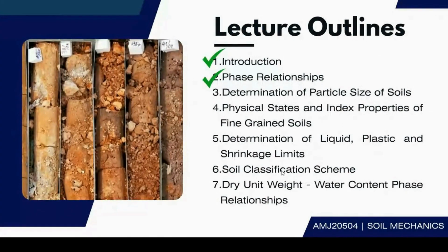So now we go to the particle size of soil. Actually, we already touched a little on particle size distribution, where the famous method that we use is sieve analysis. But before this, I already mentioned in class that we categorize two types of tests to determine the particle size distribution.